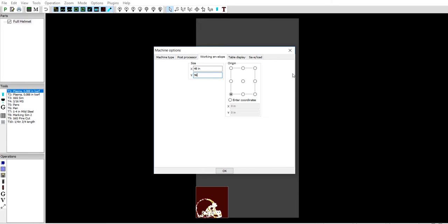On our systems, you're not going to have a machine coordinate 0, so this isn't as applicable. However, if you do want to see your machine area and take that under consideration, this is a good way to do it. It also provides another added layer of safety if you're constantly bringing in your material and zeroing out at the bottom left-hand corner of your table. Again, options for you, not a necessity, but we recommend at least having these values input for future uses. All right, fantastic. Same thing. I'm just going to change out our table display to 48 by 96.